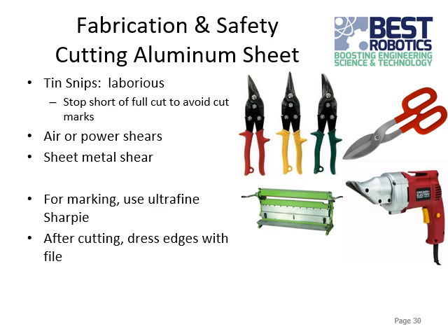After you've cut it, and this goes for the previous things too, I should have mentioned, you want to clean up the edges. With the metal, you can use a metal file to clean up the edges so there aren't any sharp burrs on it. With things like plastic or wood or whatever else you're cutting, you can clean it up with a piece of sandpaper. You can use some of that for metal too, to soften the corners a little bit. But a file works pretty well for cleaning up the metal edges.